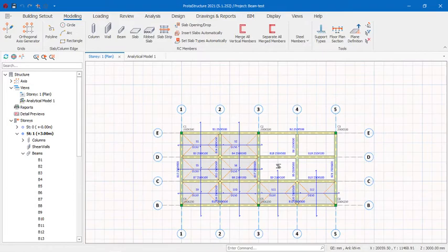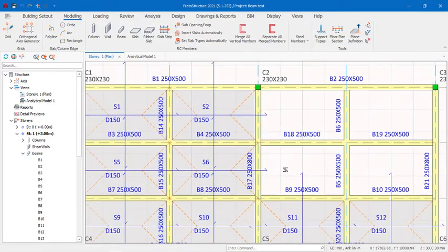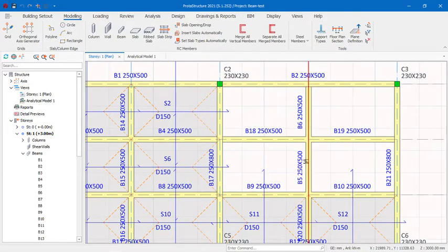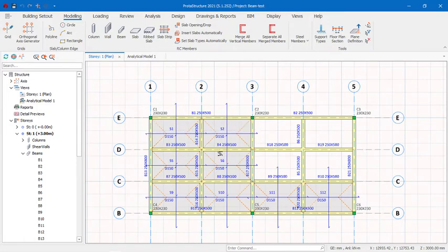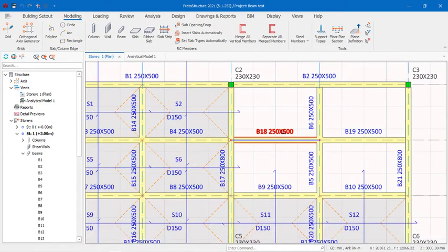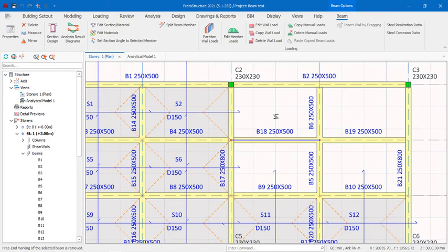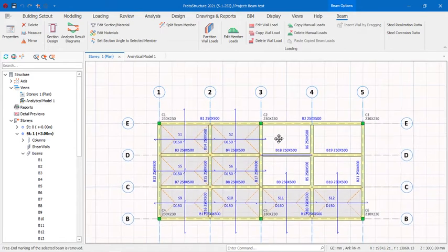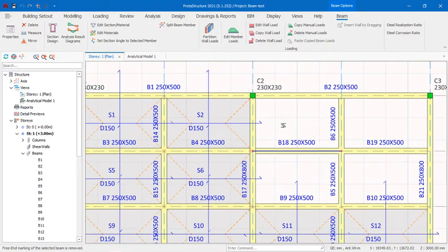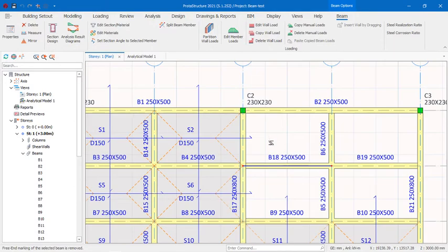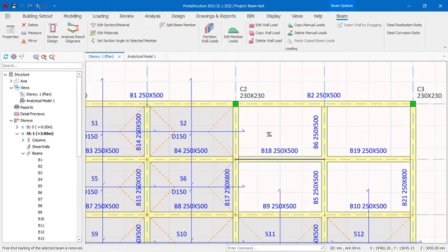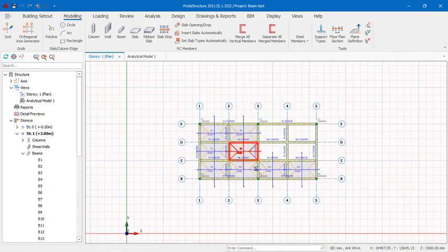So that's another thing you have to watch out for when you make your model. You have to make sure that all these beams that are connected, that don't have a column, you define them as being supported at both ends, because that's how the software will read it properly, so that you can have a result that will best reflect your intention as an engineer.